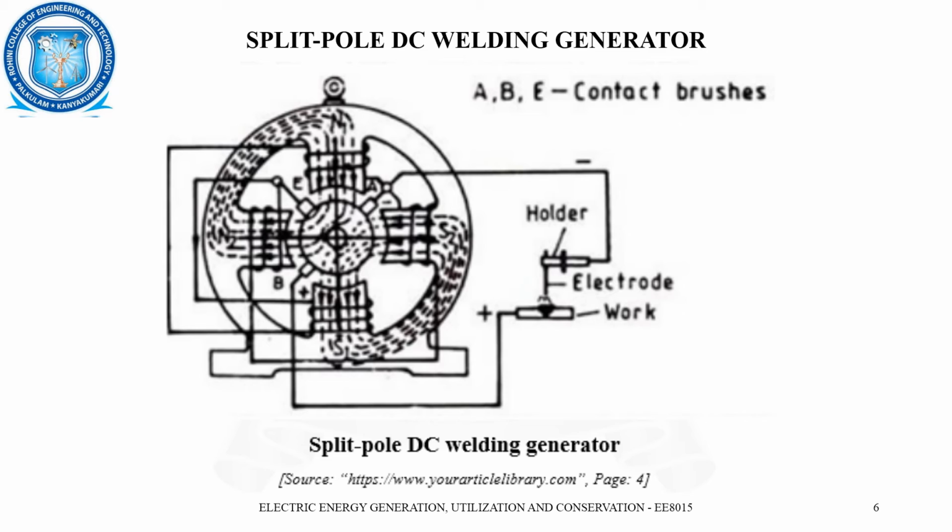The magnetic poles N1 are so constructed that they operate in conditions of magnetic saturation, and the addition of armature magnetic flux cannot increase it anymore, much like a saturated saline solution. You cannot dissolve any more salt, isn't it? Likewise, it will have the maximum magnetic saturation level. The magnetic flux of the armature, which opposes the magnetic flux in the poles N2 and S2, reduces this flux and in fact almost kills it.